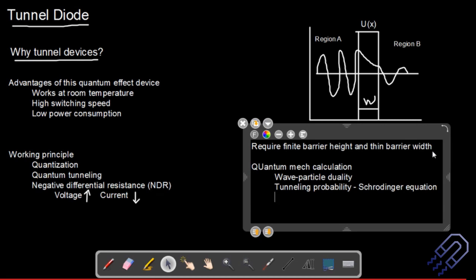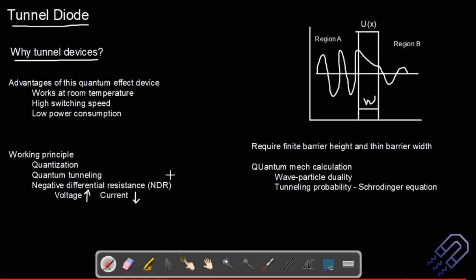And if we have a complex barrier shape, it depends on what kind of device you are doing. Here I've got a straightforward straight barrier with width W. But if you look at the picture we have seen, even if we consider something like a Schottky diode, the barrier is something like this, and this is the width. So it has different widths at different regions. The chances are that you will have more tunneling in the region where the width is less. So this is not very complex.